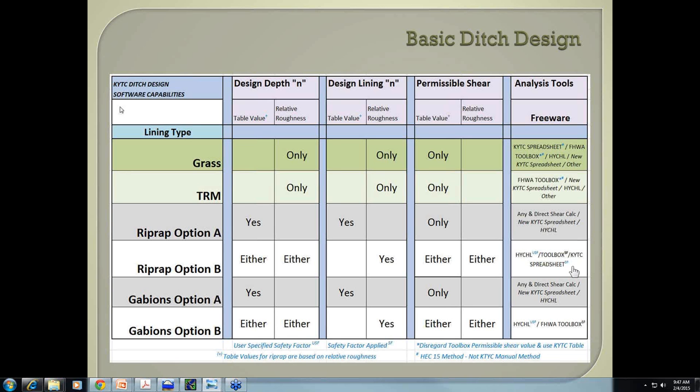And maybe as a side note to that, in HEC channel, and it really needs to be pointed out, the documentation notes that the particle Reynolds value that triggers the maximum Shields parameter for a higher permissible shear is 10 to the 5th power, or 100,000 for the Reynolds number.